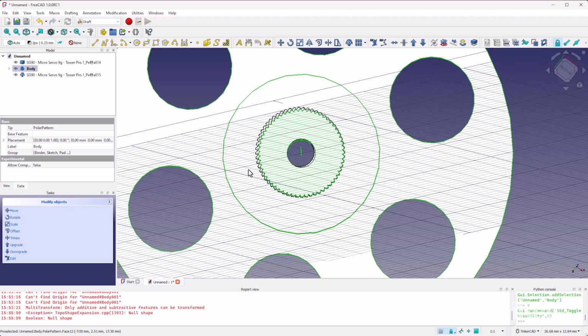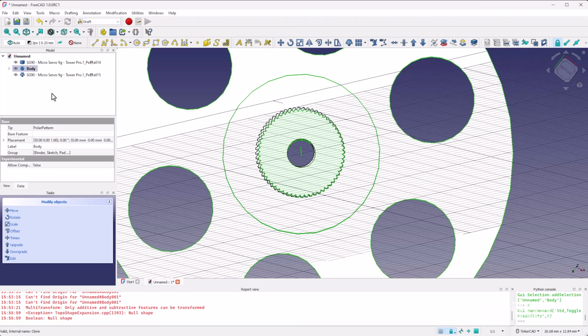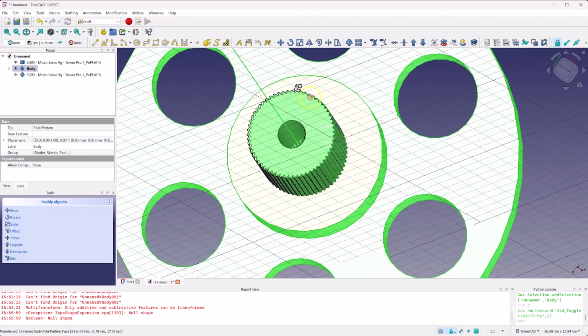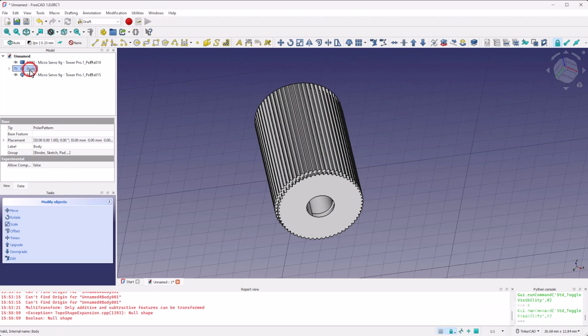What I should have done was create this scaled part first and then built the wheel on top of that. But let's say you're in this situation and you have created the part and now you need to cut, and you want to scale the part you want to cut out, but you didn't build on top of that scaled part. That is a problem. But we can fix this using the alignment tool. Once again, very not intuitive feature, but it does get the job done, and I will show you how to use it. So I'm going to hide this.